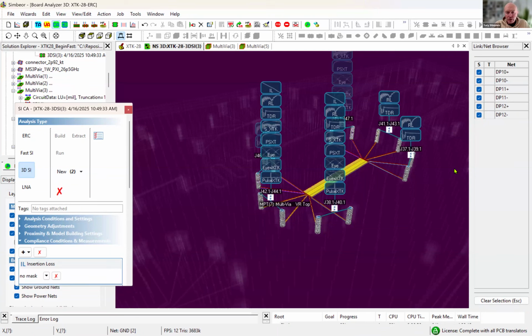But the goal of interconnect design is to make it localized, so not radiating, not interacting with others. As soon as you follow those goals, the structure becomes more and more accurately simulated with the decompositional analysis. So it coincides with the design goal, and basically, you converge to proper design. You satisfy all those localization properties, and it becomes simulatable in isolation.